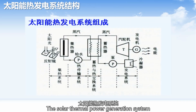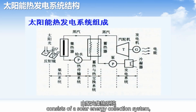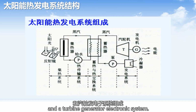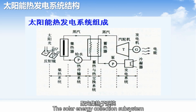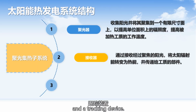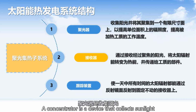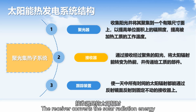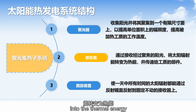The solar thermal power generation system consists of a solar energy collection system, a heat transfer system, a thermal energy storage subsystem, and a turbine generator system. The solar energy collection subsystem includes a concentrator, a receiver, and a tracking device. A concentrator is a device that collects sunlight and concentrates it, raising the temperature of the heated working fluid. The receiver converts the solar radiation energy into thermal energy and transfers it to the working fluid.